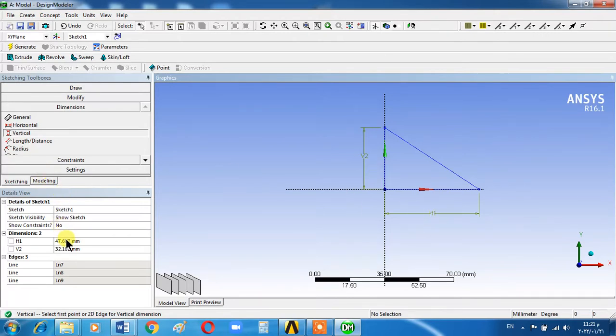When I look here in the bottom, I see the dimensions. Edge 1, I will put my numbers. Edge 1 is 40. Enter. Edge 2 is 10. Enter. Look, the triangle changed according to these two dimensions.